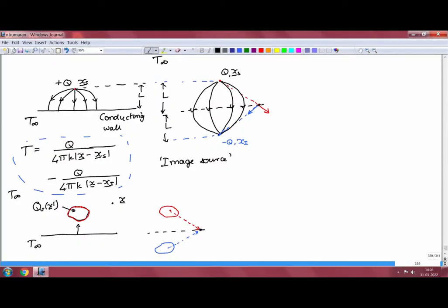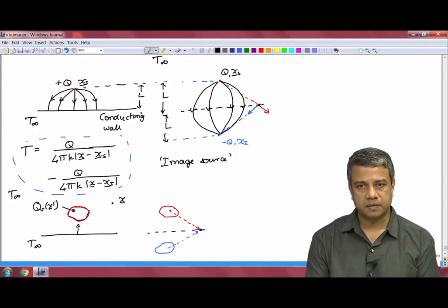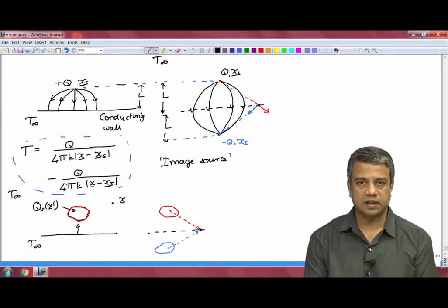In the last lecture, we were examining the temperature field due to a point source, first in an infinite domain, an unbounded domain where there are no boundaries and therefore no boundary conditions to be satisfied, and then secondly in a finite domain, where you had a boundary wall. And we saw that the boundary conditions can be satisfied by adding to the source, which is at a perpendicular distance L from the boundary, in the same perpendicular line as the source, a sink on the other side.